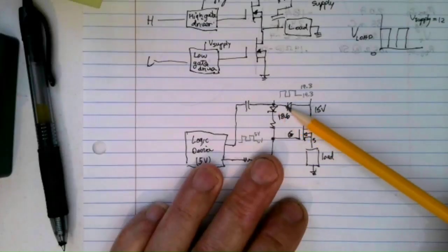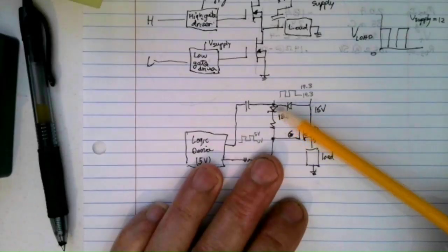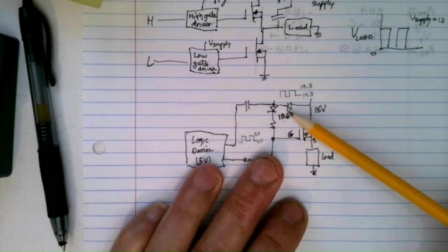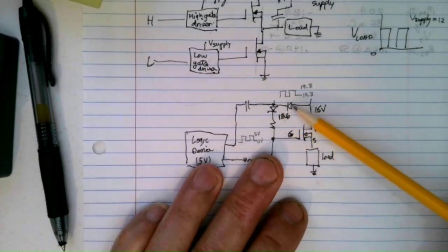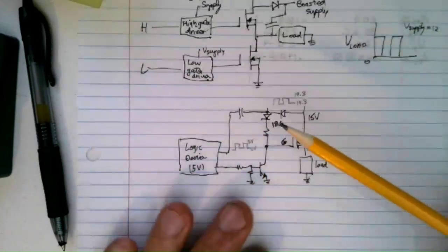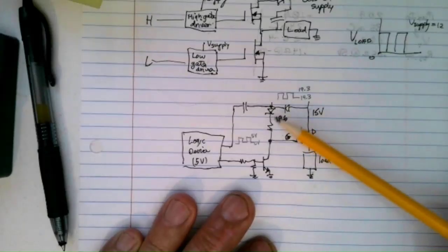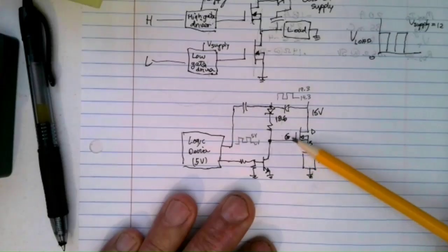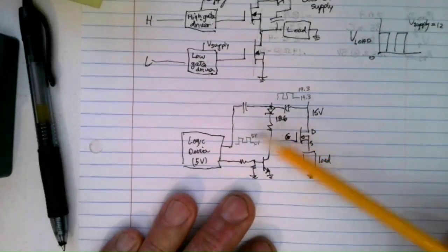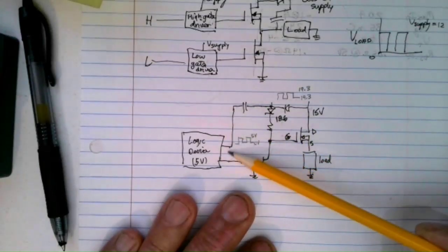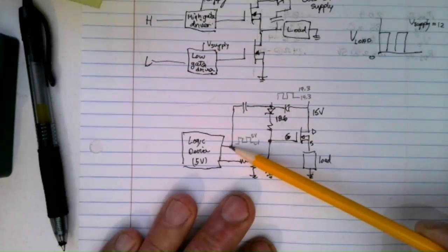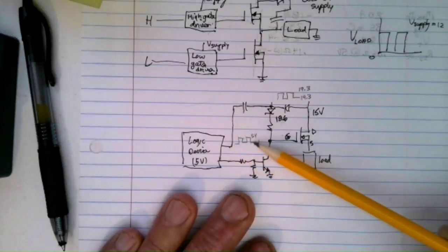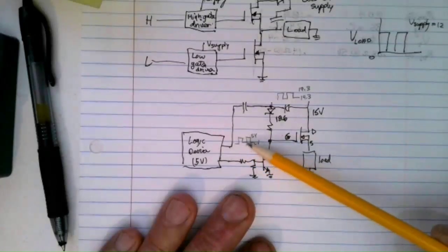Maybe if you use Schottky diodes here, you could do a little better because they only have like a 0.35 volt turn on. But realistically, if you need 20 volts or more here to be sure this guy is turned on really good, you're going to have to buffer this with a little inverter, a little BJT inverter circuit, so that instead of 5 volts peak to peak here, you can have 15 volts peak to peak.